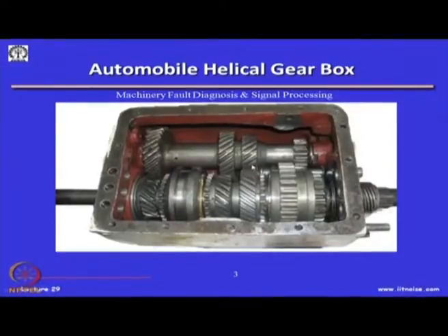because each of these gears, this tooth will deflect under load, they will get heated up because of the friction. So, there are always these gearboxes having in this casing some sort of a gear transmission oil, basically used for lubrication, to carry over the heat.